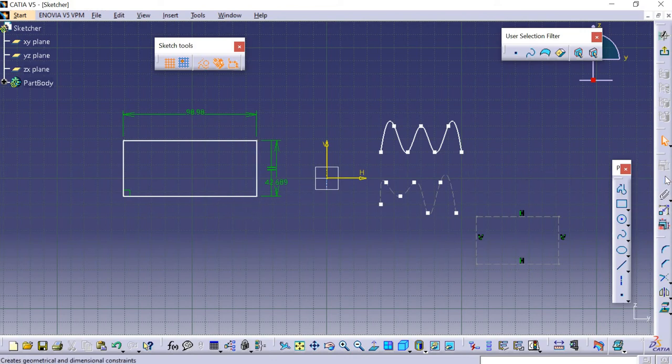Now if I constrain this element from here to here, it's 52.033, this color turns green. Same thing with the horizontal line, and when I constrain it, the whole rectangle turns green. So green is called a fixed element. It has been fixed using the constraint. So this geometry has been fixed using constraint, and hence it is called a fixed element.